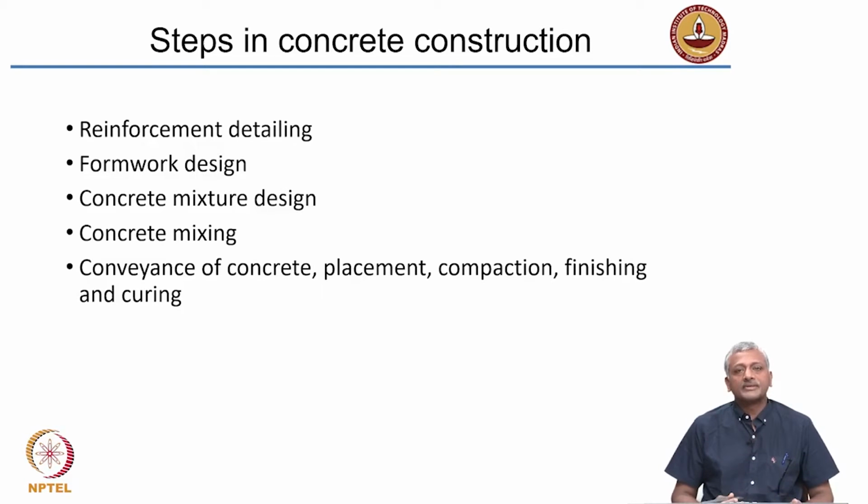Concrete mixture design involves selection of the right proportion of ingredients, primarily cement, water, aggregates, in such a way that they give a concrete mix that has a sufficient amount of workability, and of course it performs to the satisfactory level in terms of strength and durability.